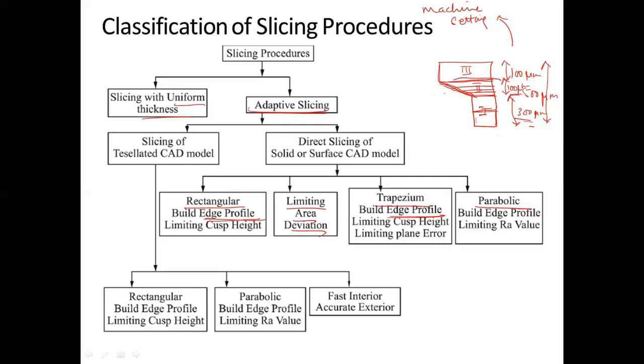Now, I'll just take the example of the second region and plot it over here. This is the second region that you generally see, which will be depicted something like this to you. But when you actually go and observe, the profile is something like this. That is why when you take your probe upon this, there is a peak, there is a valley, and there is a peak. That is why you get surface roughness. So the whole nature of the edges also determines how the slicing procedure is going to be defined.